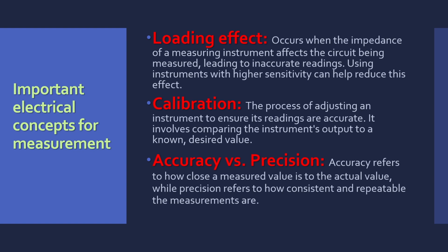So your instrument's impedance should not interfere with the measurement. So this leads to inaccurate reading. Using instruments with higher sensitivity can help reduce this effect. So if you are using instruments with higher sensitivity, you can overcome this loading effect.